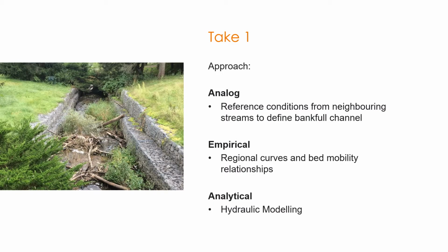The approach that we took to develop our design for Idlewood Creek included a mix of several of the design methods that Scott was talking about. For example, our analog type of approach did include a reference reach. We did find a reference style channel that descended the Grand River Valley wall, and we did evaluate that channel to define some of our dependent variables.